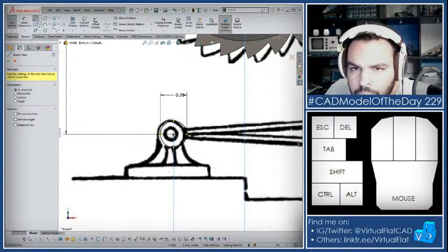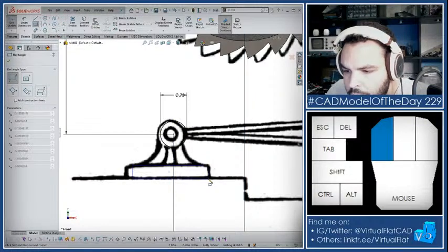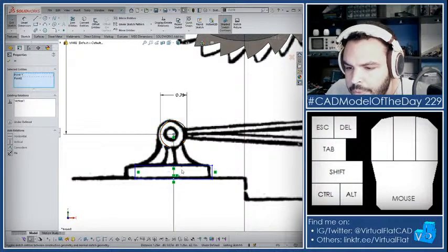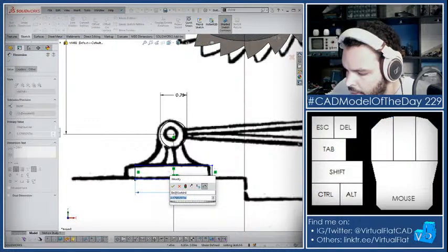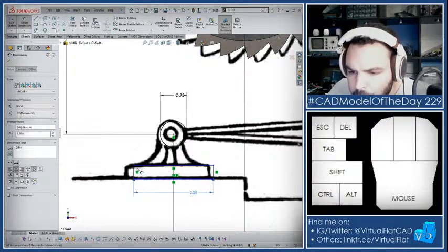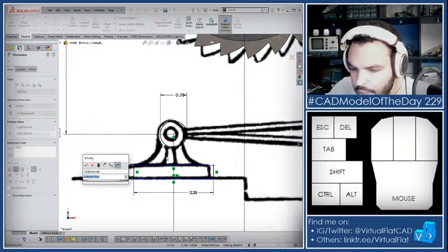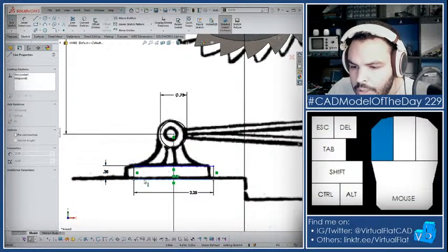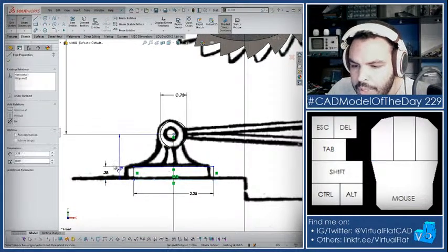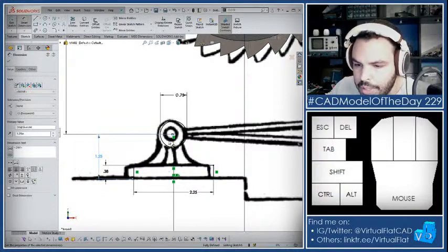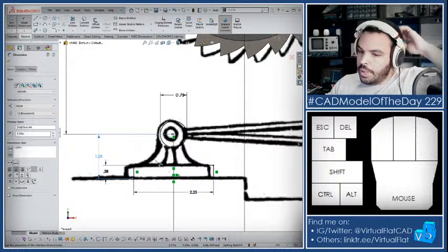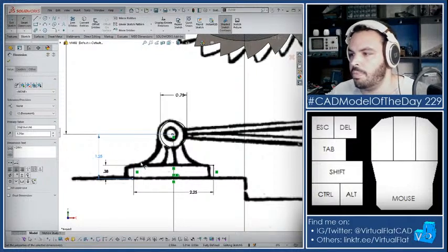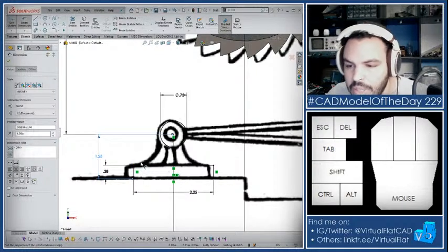All right, so yeah, let's get a rectangle, and then I'll bridge those together and trim. So I can say, select that midpoint, vertical, maybe 2.25. This is a guess. Height of 0.375, 3/4 of an inch. All right, and okay, we still need its offset from here. 1.25 looks like a good value. And yeah, that's literally what I do for all of these. I just have the picture and I just kind of try to make the values fit with numbers that make sense, you know.